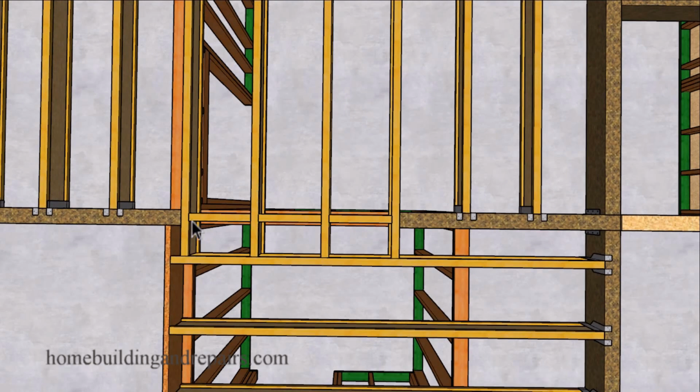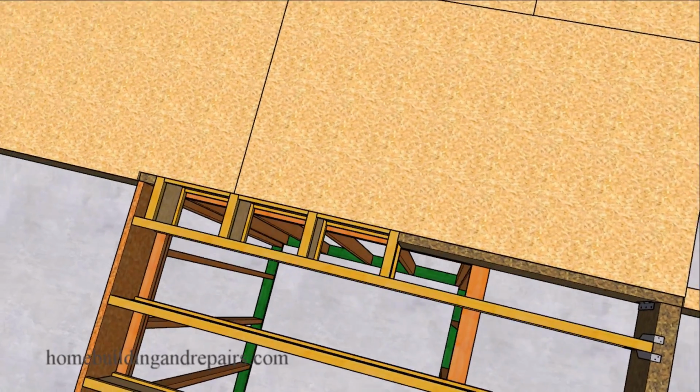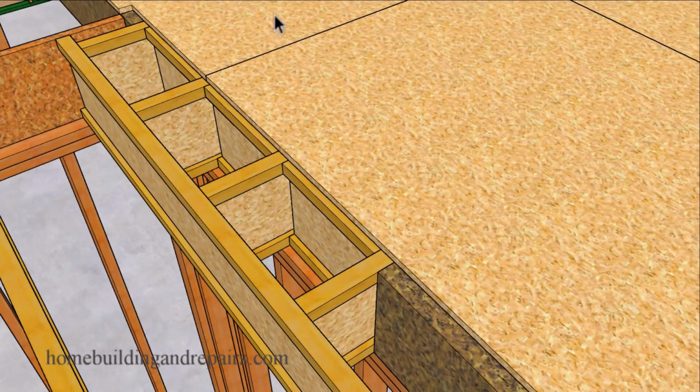And in some cases, we will need to position the blocks in a certain spot to work with our subflooring. And you can see here where the subflooring is sitting half or centered on top of the block, so that we can install the next subflooring to create a nice solid connection between the two floors or two sections of the floors. And I went ahead and ran these joists a little bit longer. I like doing this. However, you can always stop them here if that's going to work better for your project.